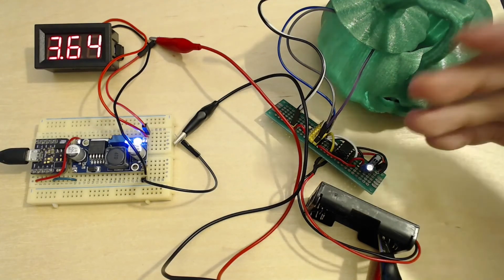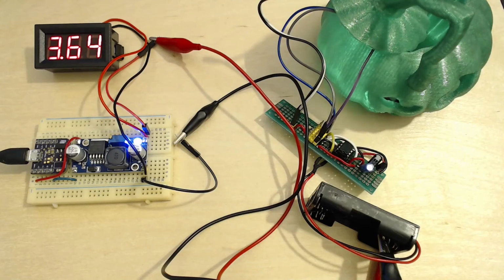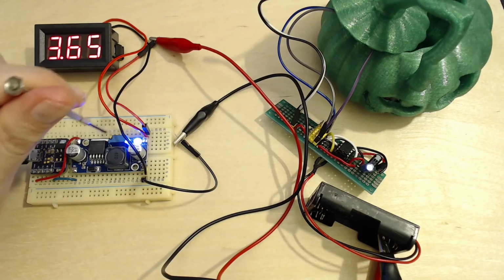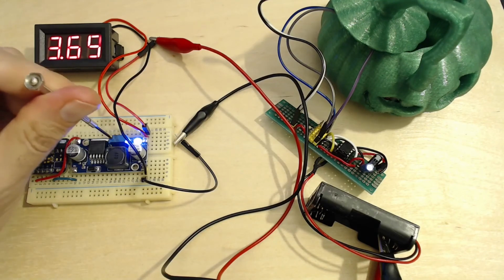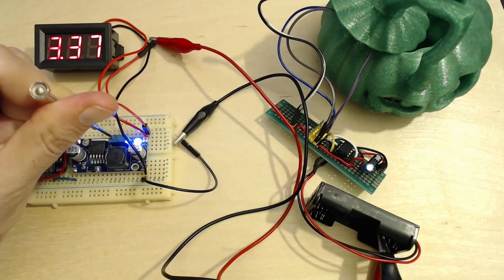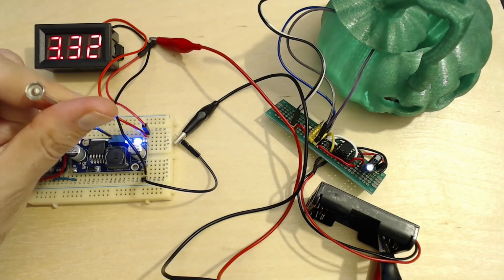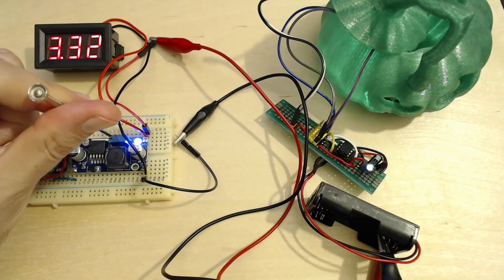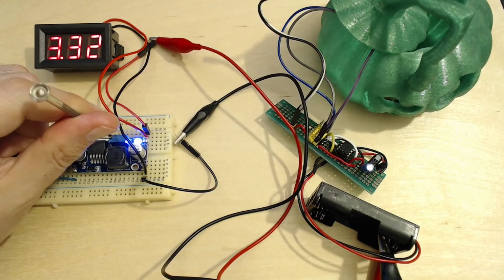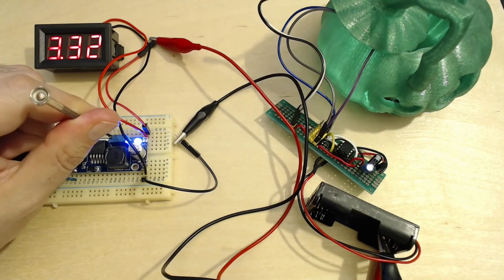Then there is motion. The light comes on. When there is no motion, it turns off by itself. Now, below this point is where we want our cutoff to happen. So we will go down to 3.3 volts now. This is where our batteries would be depleted, and it started glowing right away. There's a bit of an interesting spot here. Now our motion sensor stopped working properly, but we still haven't reached our cutoff voltage.